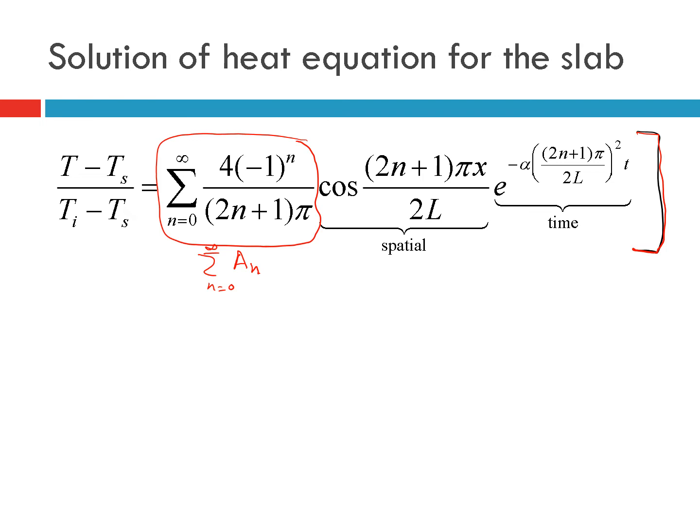You notice the solution has non-dimensional position, non-dimensional time, and non-dimensional temperature. They all have interpretations. For example, T minus Ts, the temperature change, is in relation to the boundary temperature, Ts. So T minus Ts is the amount of change that is yet to happen.